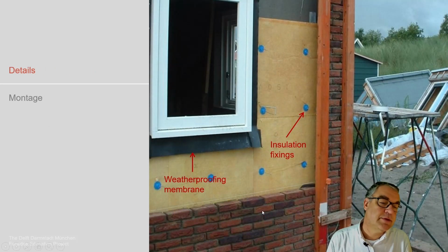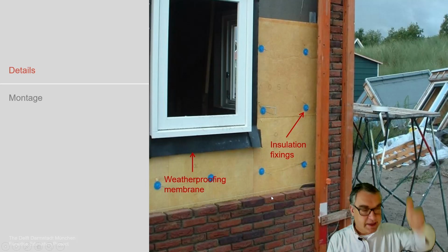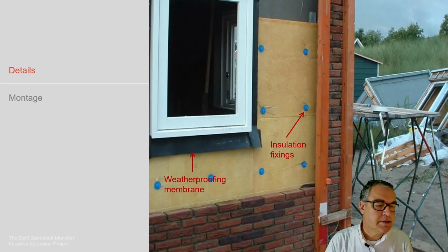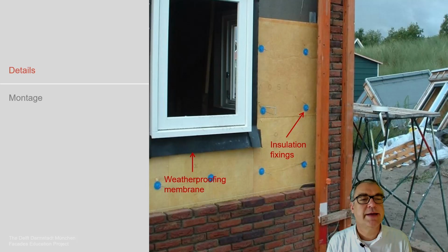This is the more detailed situation. We see the outer masonry structure, we see the insulation, we see the insulation fixing with the plastic cover cap, which keeps the insulation in position, and then this metal rod, which is brought into the masonry structure and keeps the masonry structure in position, keeping the distance for the cavity in position as a system. And then of course at the top of the picture we see the concrete structure being brought in position.